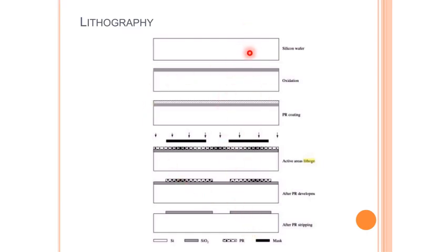So starting from the pure silicon wafer, then the silicon oxide layer, then the photoresist material, then using the photomask or mask, generating the pattern with the help of UV rays. After etching, the photoresist material is removed from the selective places, and now selective windows have been created where exactly the doping process or some impurity introduction can be done. This is in short the photolithography.